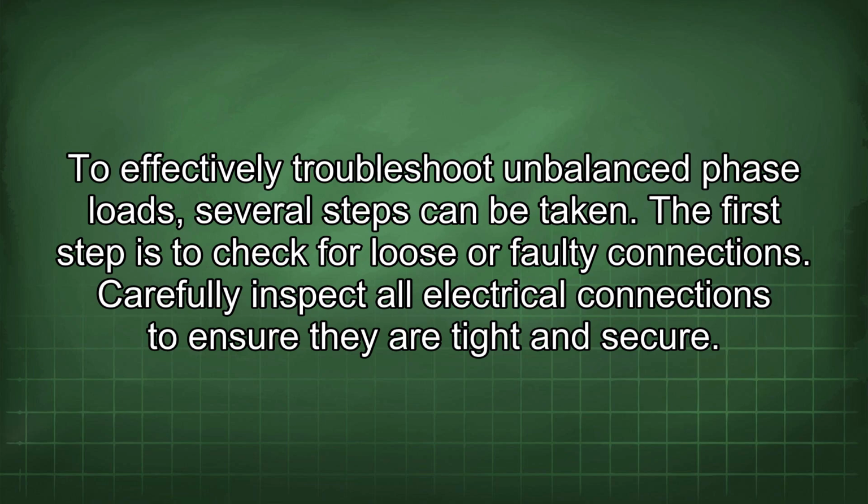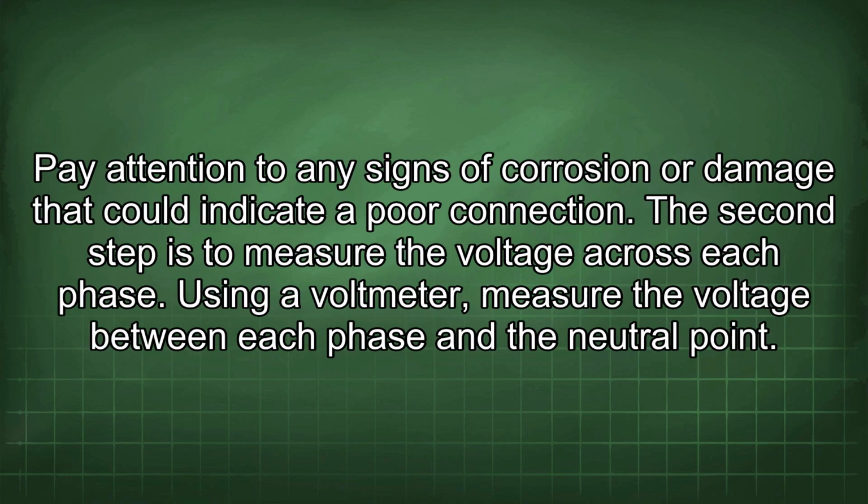To effectively troubleshoot unbalanced phase loads, several steps can be taken. The first step is to check for loose or faulty connections. Carefully inspect all electrical connections to ensure they are tight and secure. Pay attention to any signs of corrosion or damage that could indicate a poor connection.